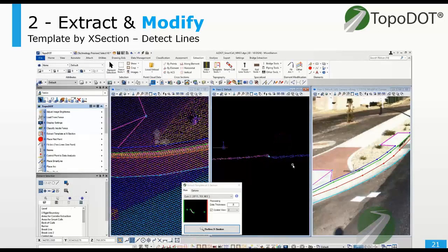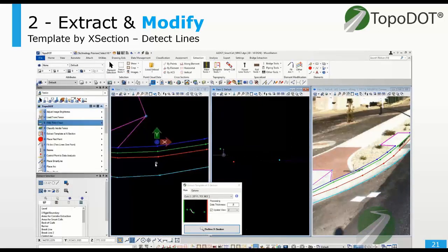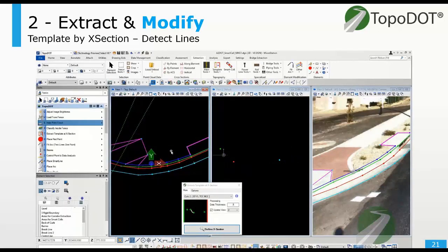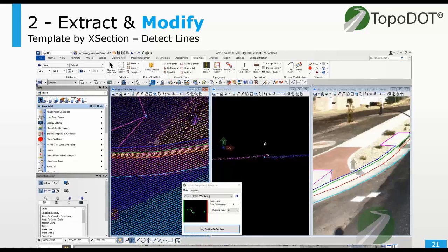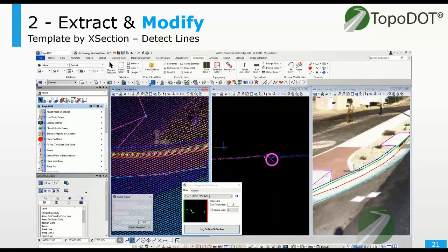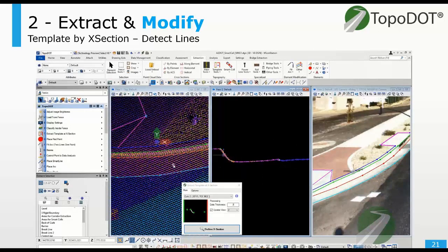So the lines are going to be automatically updated, and you're going to get the added benefit of verifying fitment right away via the update view, which, if I back this up, the update view is view 2 here in this case, which can be followed by any necessary adjustments with the Quick Adjust Line Work tool. Okay, so this ultimately is just going to allow for faster modification times. So there we jump right into the Quick Adjust while we're in that inspection or update window there.